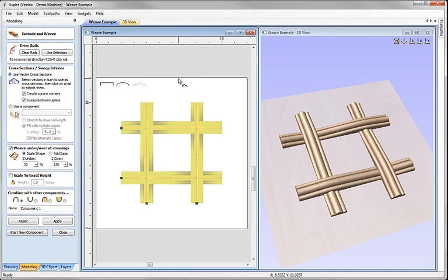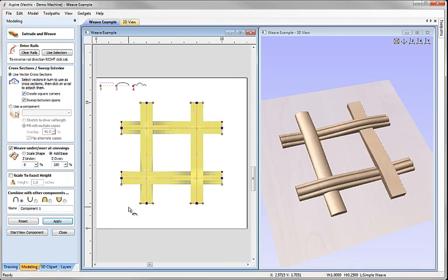Even though we're now creating a weave, we can still access the other parts of the function. For instance, we could take that cross section we've got selected there, click to assign it to the rails, and then I could come up, select this cross section, and we could click that end, and then I might select this cross section and click that end and that end. So now what we're going to do is sweep this cross section horizontally, and we're going to have the round cross section down here and then the rectangular cross section down here. Let's just click to make sure we're still on the add base option and hit apply. And then we can see the result of that now in the 3D view.